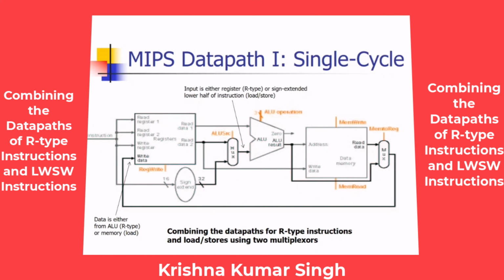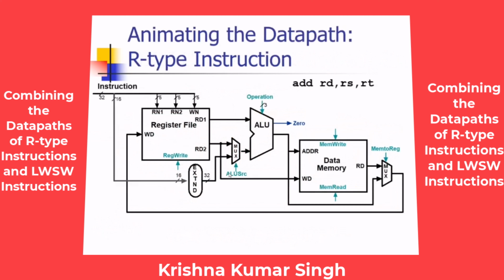Okay. Let's combine the data paths for our R-type instructions and the load and store instructions by using 2 multiplexers, one here at the input of the ALU and one here to select between the type of data that we are going to store back inside the register file. Is it coming from the result of our ALU, or should it come from the data memory? So as you can see, we inserted 2 multiplexers here. Let's check the execution of each instruction in this new data path.